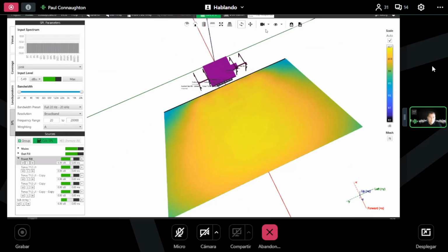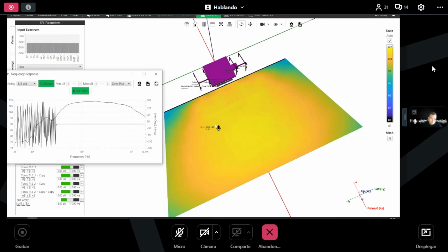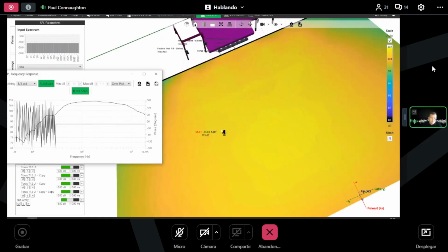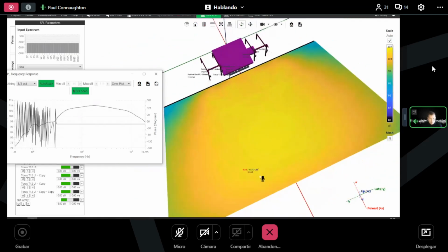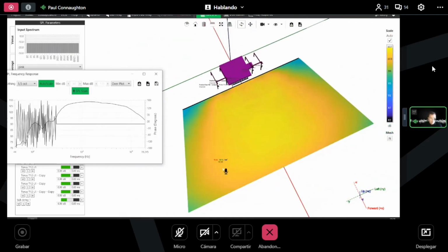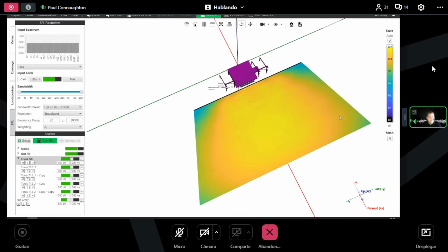If we go through with our microphone and our point, we can see that we've probably got 104 to about 106 dB throughout the audience area, 106 on axis in the center, 105 up to 104, all the way up to the back of the audience areas, 105, 104, 103. So really nice coverage all the way throughout our audience area. Obviously going out to the extreme sides, we're going to get some attenuation as you would expect over distance, but predominantly that's a gig. As far as I'm concerned, it's really good. That will do the job.